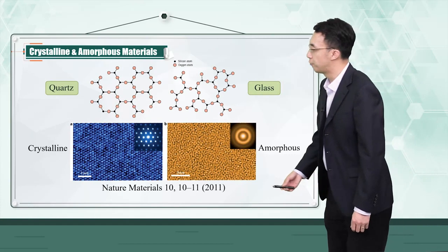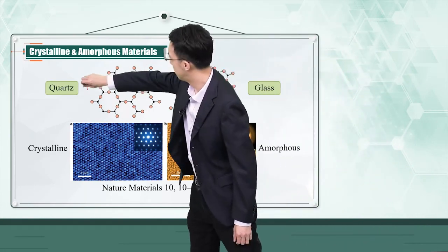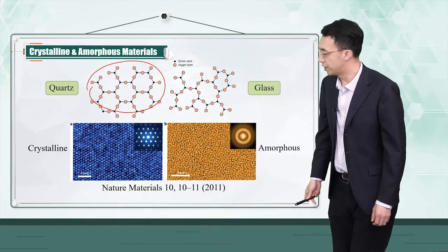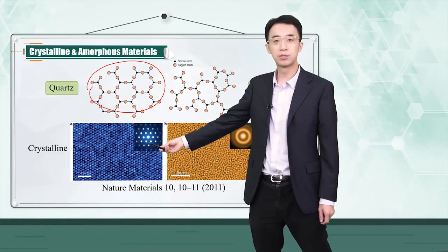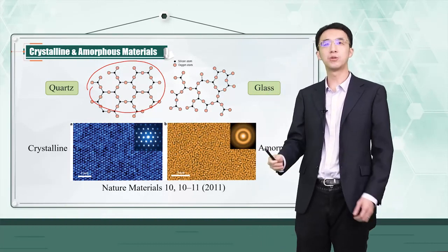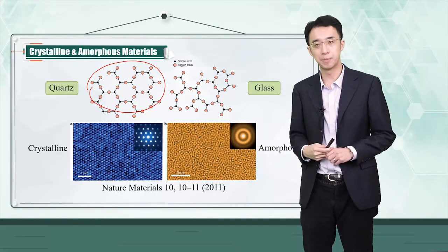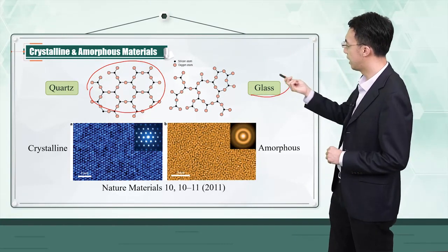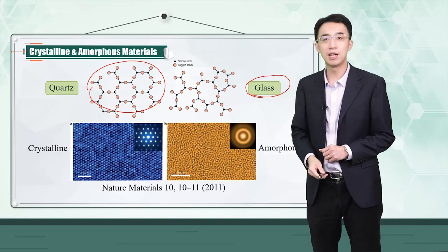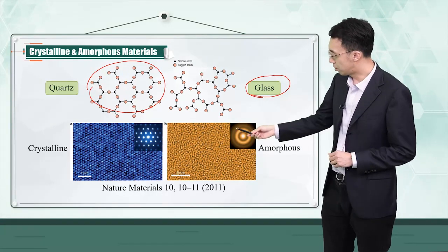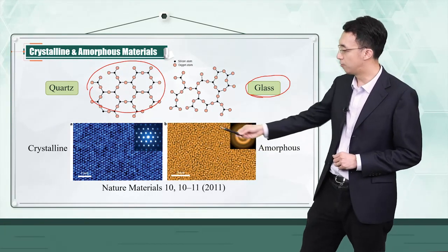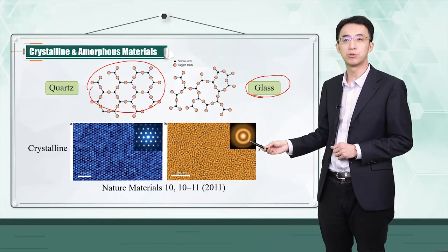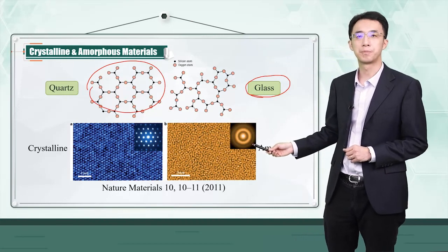So in general, if you have a crystal under TEM, electron beam diffraction will give individual diffraction spots that correspond to particular parallel atomic planes. And instead, if you have an amorphous material, for example, if you are doing TEM electron diffraction on glass, you generate circular continuous rings instead of these individual diffraction spots. And such rings are characteristic of amorphous structure.